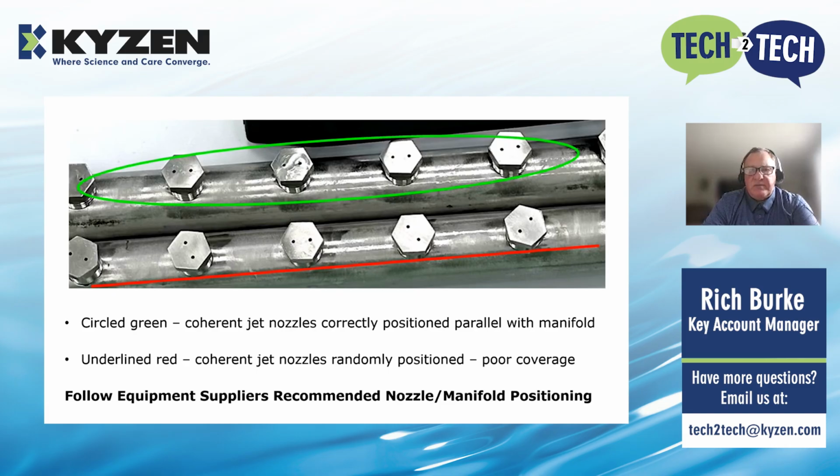So again, it's very important that we position our nozzles once we've cleaned them. Obviously step one is clean them, but step two is to make sure that we reinstall the nozzles into the manifolds as they're intended to be done.